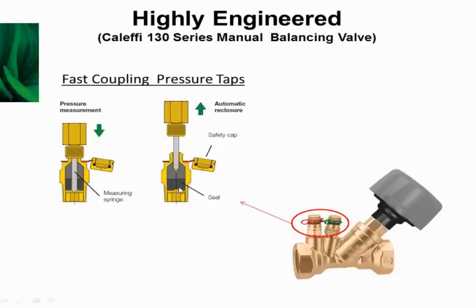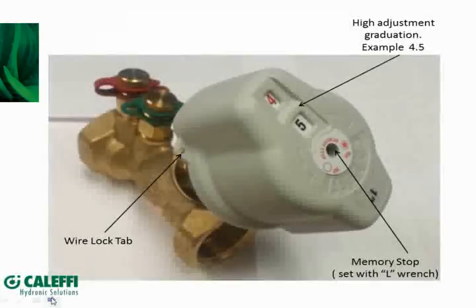Now, a word of caution: as you pull these needles back out, do it slowly to allow time for the EPDM to shrink around the needle as you're pulling it out. If you pull it out too fast, there will be a momentary exposure of the hydronic system to ambient, causing a squirting and problems associated with that. So just a little point for you.